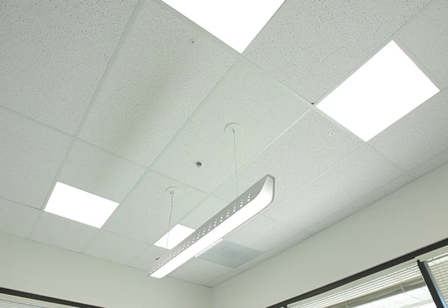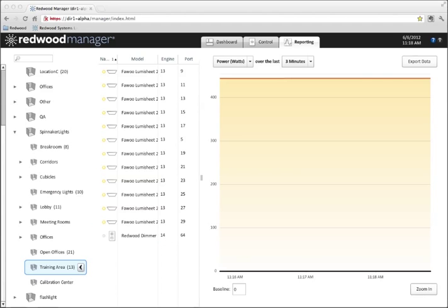The Reporting tab is where you view the impact of various lighting policies. Currently, we see the total watts used in this room is over 400. Initially, we're going to enact our best practices policy of running the lights at 85% of maximum. This results in a relatively small decrease in light level that is barely perceptible, but results in about a 30% reduction in power consumption right off the bat due to the efficacy of LEDs improving disproportionately when dimmed.